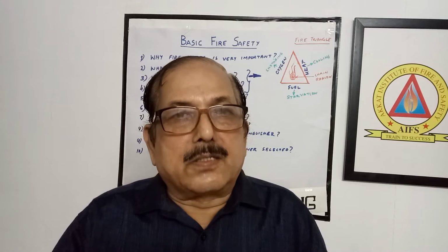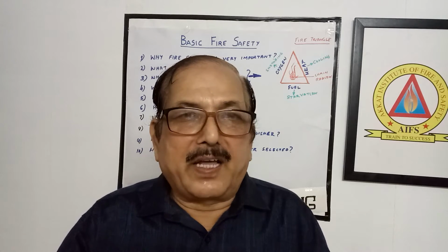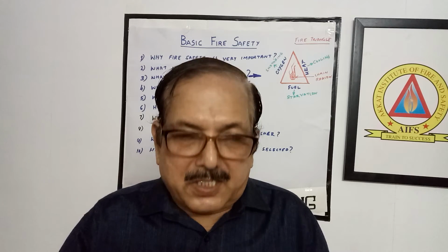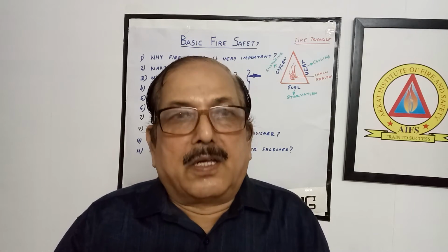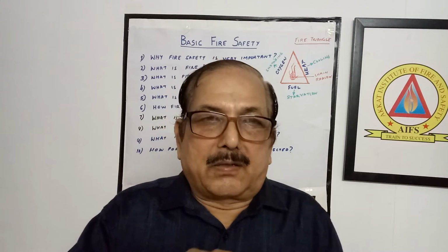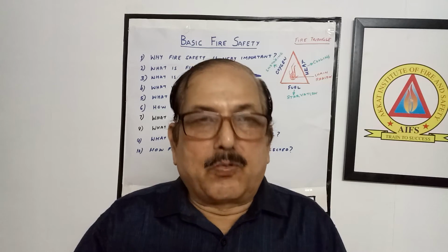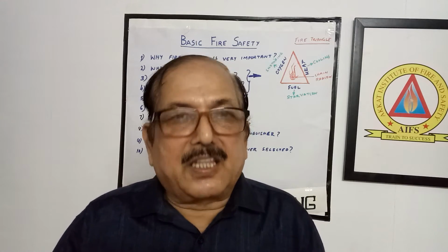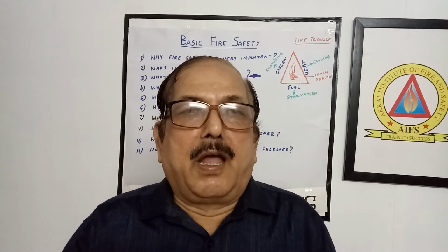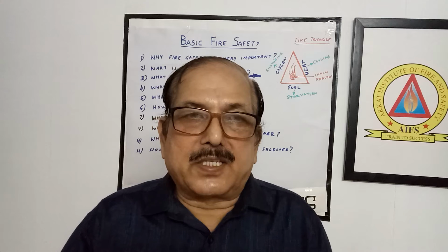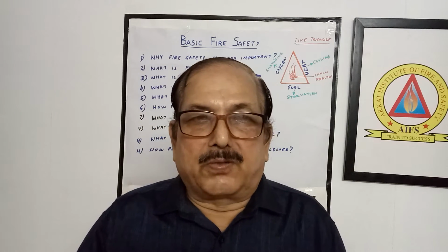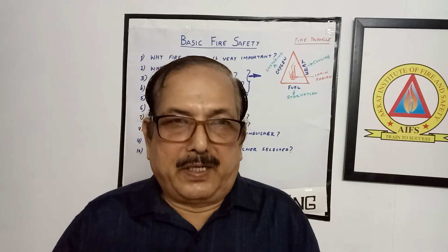But nowadays most of the extinguishers are not like this. The extinguisher cylinder itself has air pressure. On most cylinders we can see a small dial, a small pressure gauge, so we can check the gauge. By seeing this gauge, we can tell whether the fire extinguisher has sufficient pressure or not. Except for the CO2 extinguisher, we do not have any gauge.